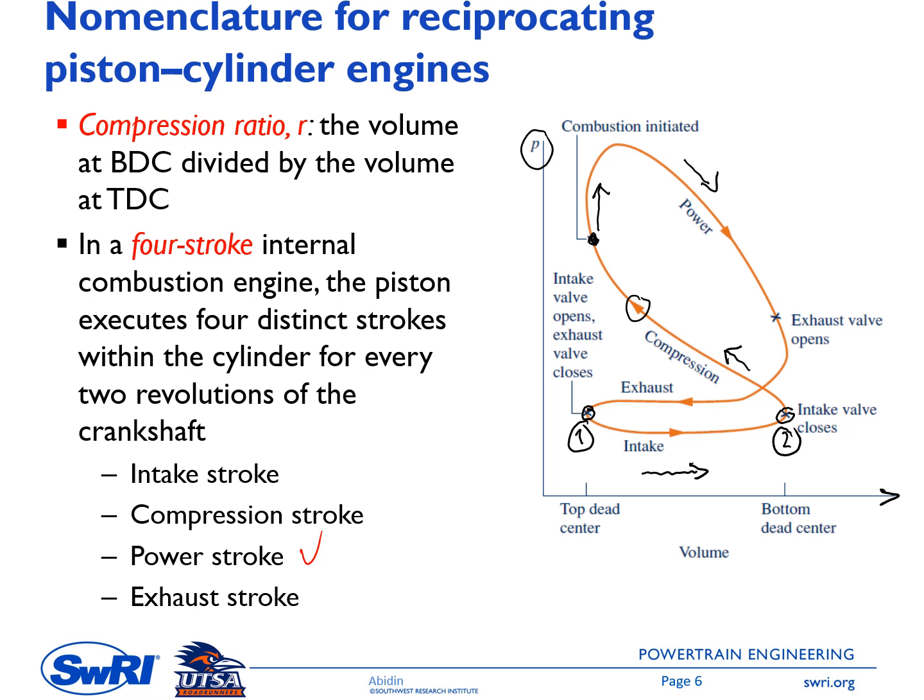bottom center, and this is the power stroke. So there will be an expansion from this high pressure and temperature gas. There is a transfer of energy from the thermal energy into the mechanical energy to the piston, and then it will be forwarded to the crank mechanism and so on. The piston moves down, and then at some point there will be a timing when the exhaust valve opens, okay, exhaust valve open, and the burnt gas is discarded out of the combustion chamber.